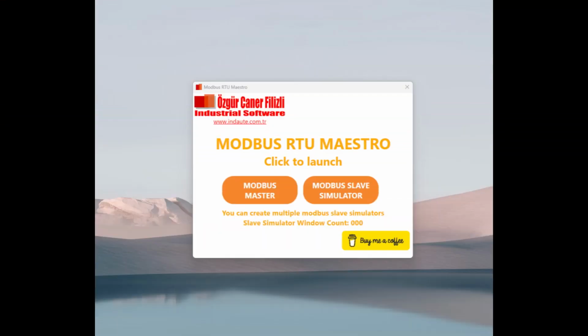Modbus RTU Maestro is a Windows application designed to emulate a Modbus RTU master and multiple slaves. When you launch the software, the main window allows you to choose between the Modbus master, Modbus slave interfaces, or both. Please note that you need real RS-485 hardware to communicate with external devices, or between the Modbus master and slave interfaces offered by the software.